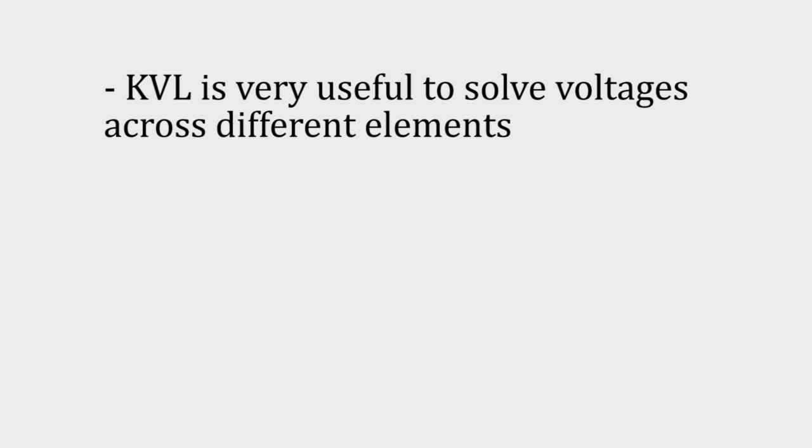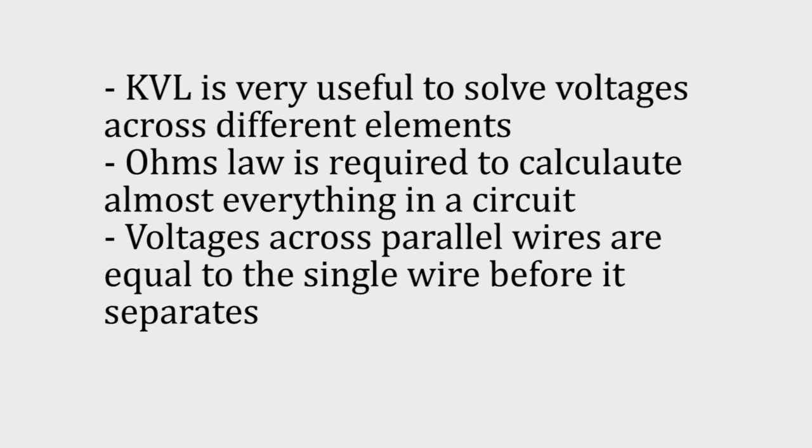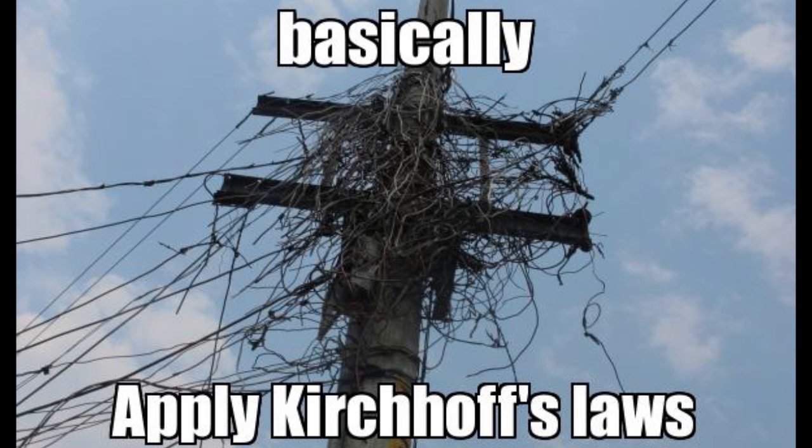To summarize, Kirchhoff's voltage law is a very useful tool to solve voltages across many different elements. The use of Ohm's law is required to calculate almost everything within a circuit. Voltage across parallel wires is equal to the single wire before it separates. And finally, for the last example, basically, all you need to do is apply Kirchhoff's law.